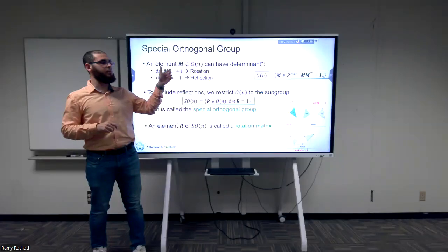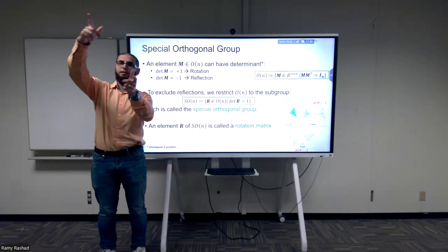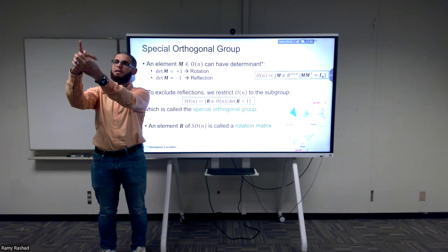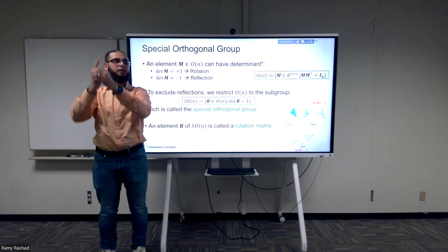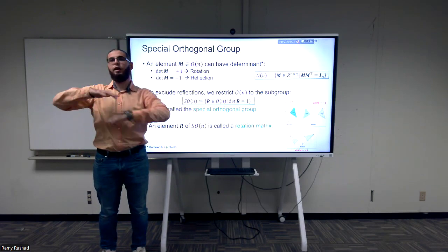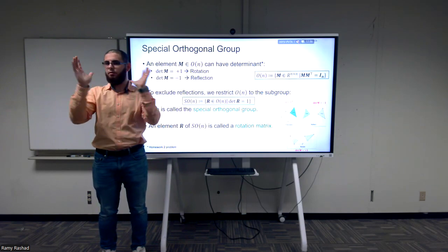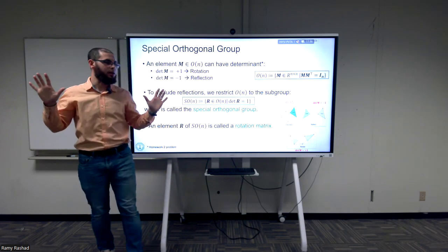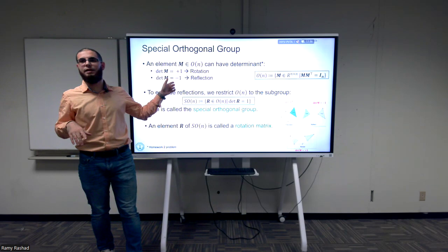And we said that the determinant of +1 represents a rotation: I take a rigid body and rotate it. Of course, rotation means the point is fixed, so I'm not translating. Or I can do reflection. If I have robots moving around, have you ever seen a robot that reflects rigid bodies? Is this something physical? This is not part of the Euclidean space we're living in. There are no reflections, so we want to rule out these reflections.